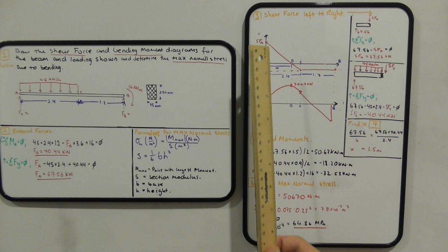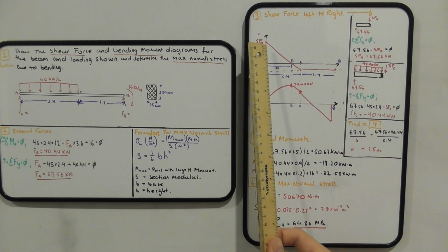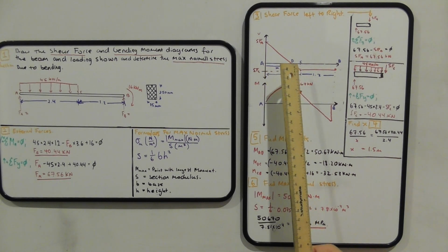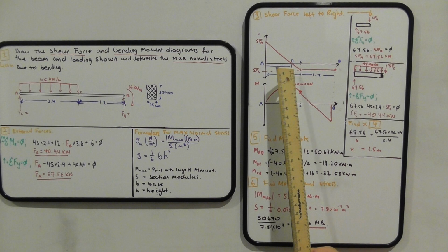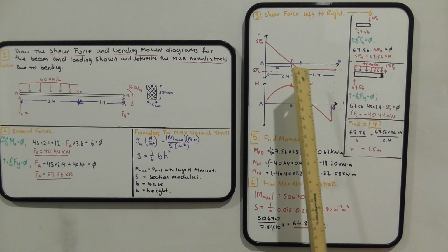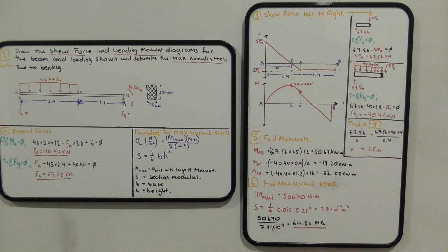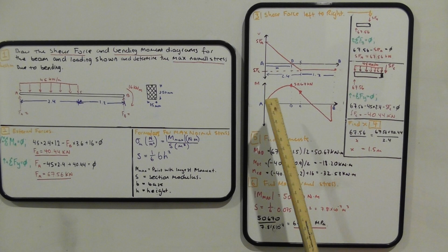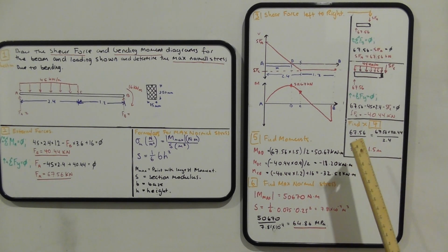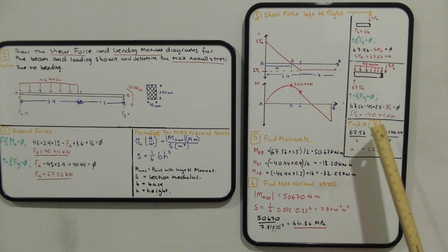Now, when we calculated SFA and SFC, we identified that there's an X here from A to D, where the line crosses over the axis and goes from the positive to the negative. So we need to find that X because it'll be crucial for us to identify the moments in order to draw the moment diagram. The way we do that is balancing of the triangles.